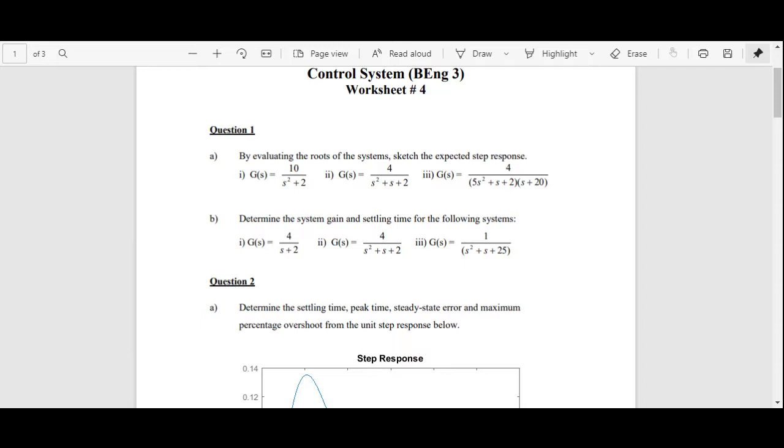It's on the left. I agree with you that it's on the left. And so is the system stable? I hear you say it's not stable. Why would you say that? Given that the poles are on the left hand side of the imaginary axis, it's stable. So we want to remember that once the poles are on the left hand side of the imaginary axis, or another way to put it, if the real parts of the pole or poles are negative.